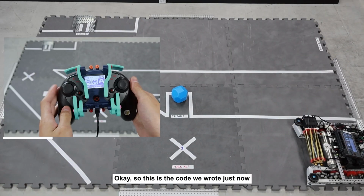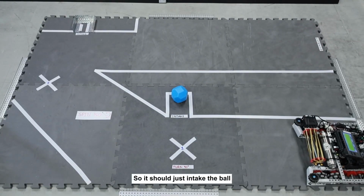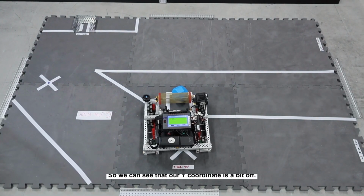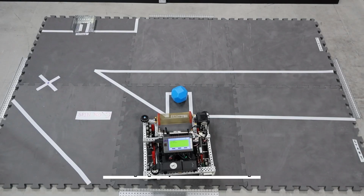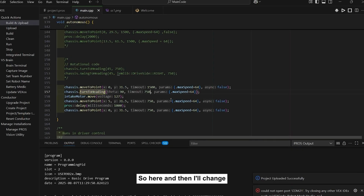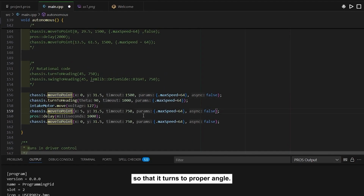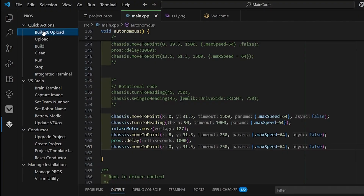Okay, so this is the code we wrote just now, and we're gonna test it. So it should just intake the ball. So we can see that our Y coordinate is a bit off, and our robot doesn't turn all the way, so we're gonna adjust the timeouts to be longer. So here, and then I'll change this timeout to 1000 instead, so that it turns to a proper angle. And then we're gonna change this move to point, so we're gonna add more on the X, so I'll go 8 instead, and now we can retest.